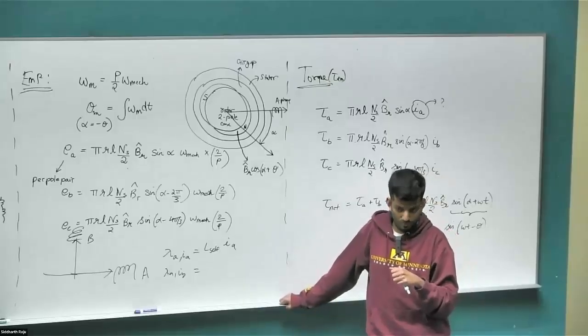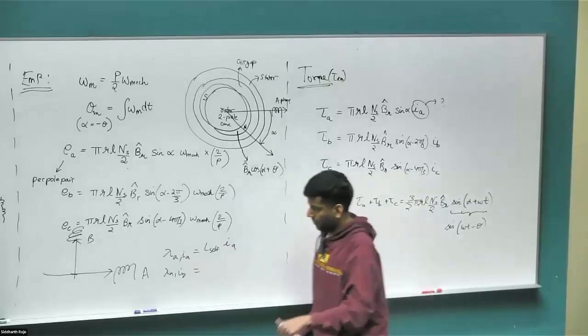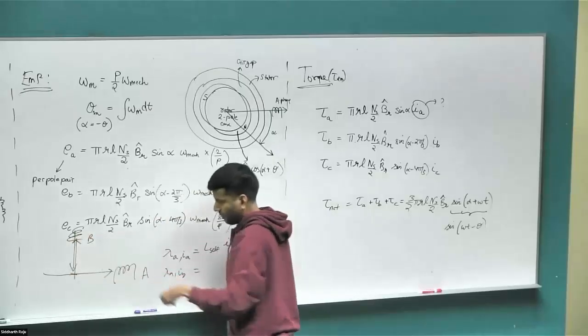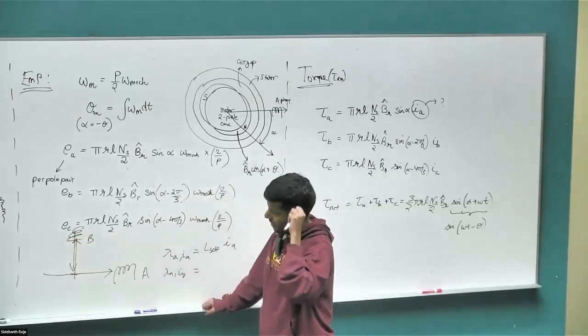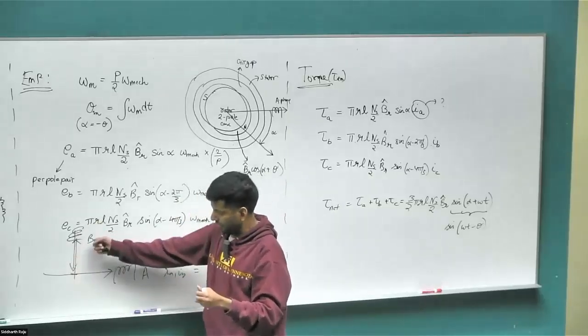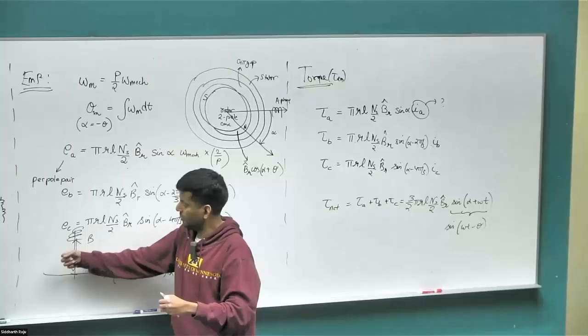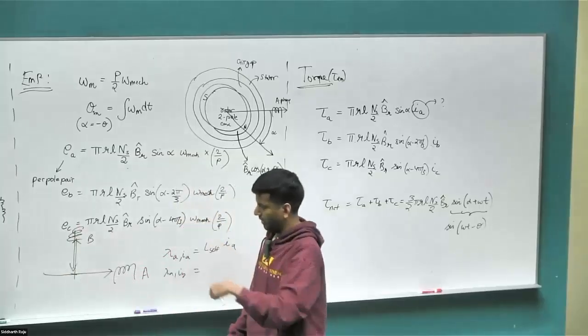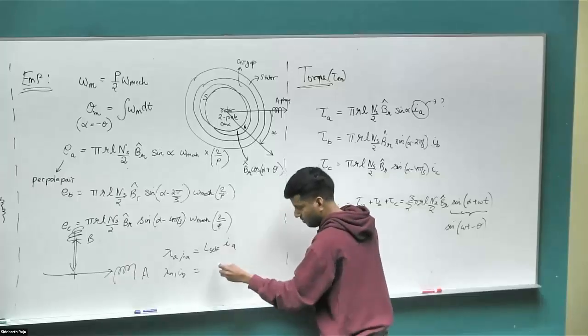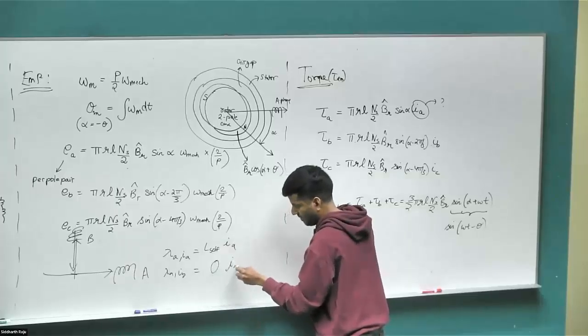It's zero. Why? Because they're offset by 90 degrees. Perfect. So basically all the flux, again, the diagrammatic version that we saw there, all the flux due to this will be vertical in direction. In reality, it will be sinusoidally distributed. Half of it will couple in the positive B field, half of it will couple in the negative B field, effectively making it appear as if it's all vertical component without anything linking along the horizontal coil that we have there. So this is just 0 times IB.